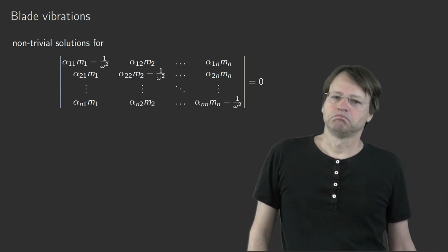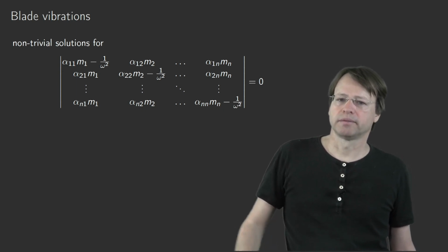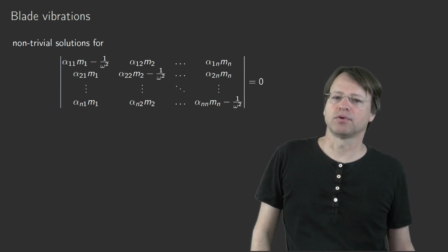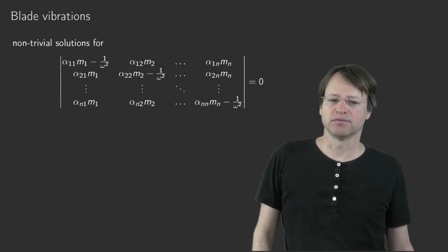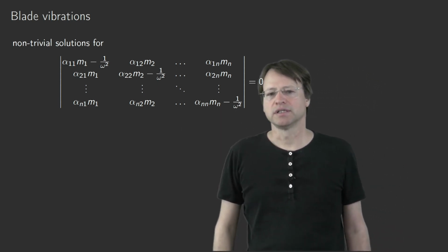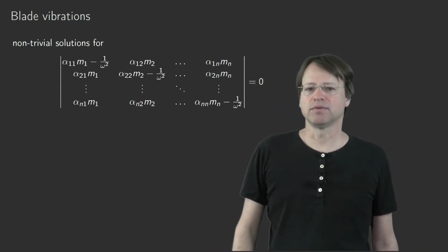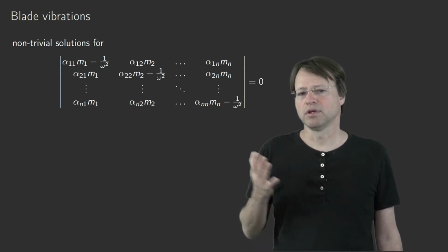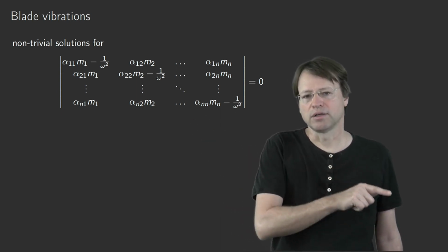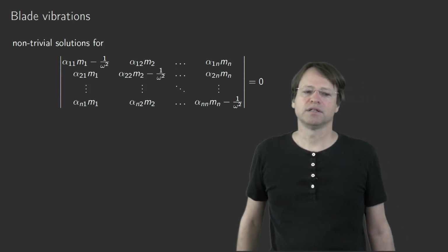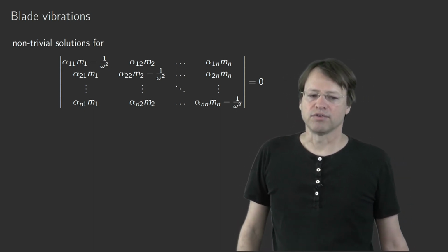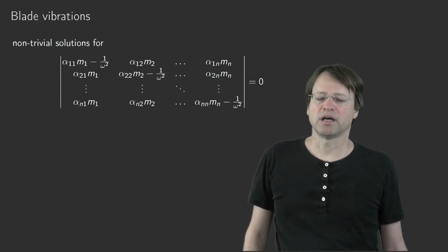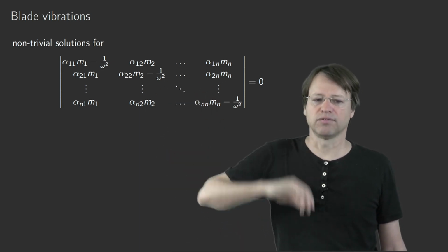So, you would get the eigenvalues from solving that eigenvalue problem here, for solving for omega squared, 1 divided by omega squared, for example. The solutions would be omega 1 squared until omega n squared, and there would be n natural frequencies. However, there is much more to tell about the eigenvalues of that matrix here.